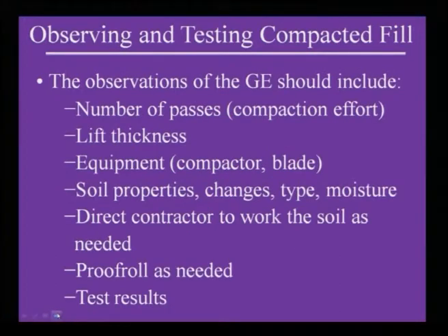Then observing and testing compacted fill: number of passes, meaning compaction effort, then lift thickness, then what equipment, compactor and blade, soil properties, changes, type and moisture, directing the contractor to work the soil as needed, proof roll as needed, and also test results.